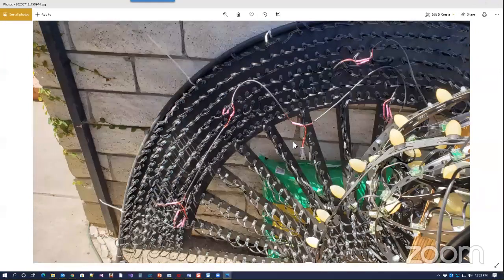So I power inject about every 200 pixels, because remember, power flows in all directions. If you think of water, if you pour it into a dish, it's going to spread out. It's the same with power. It's going to go in any direction that's the least path of resistance. So wherever it needs it, it's going to flow to that, which is why I add jumper wires, to allow that power to flow through the entire prop based upon where it's actually needed.